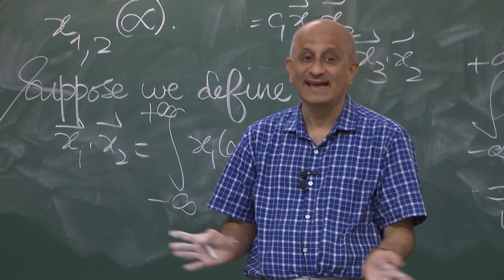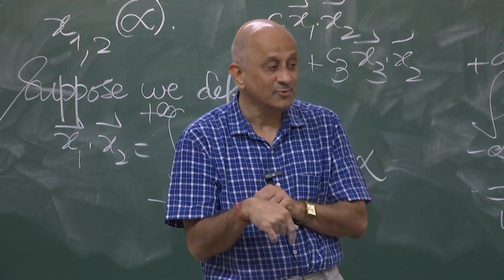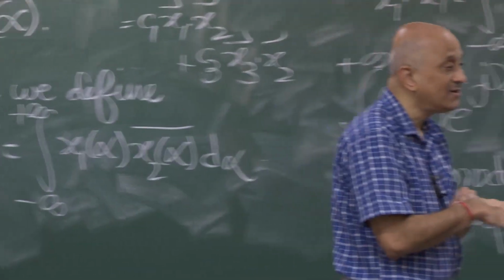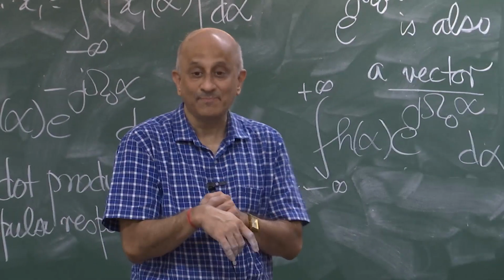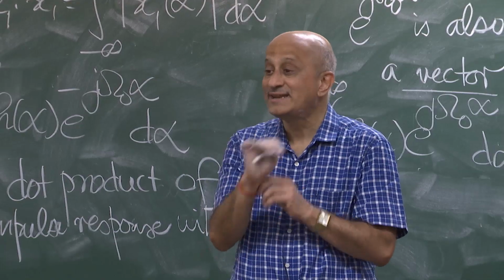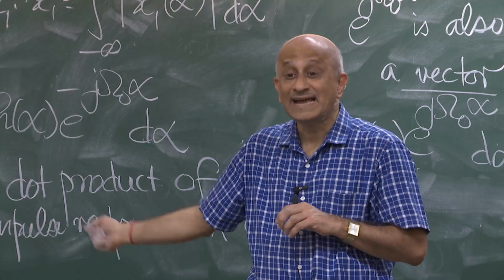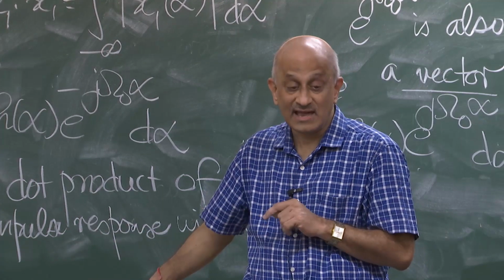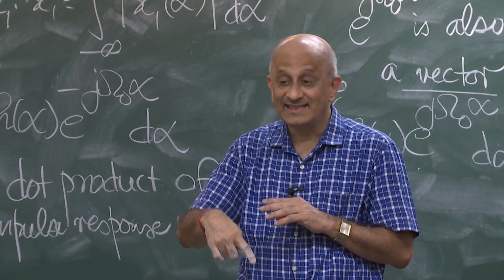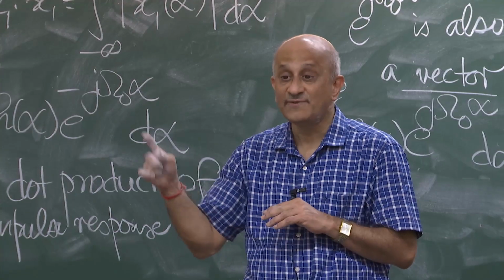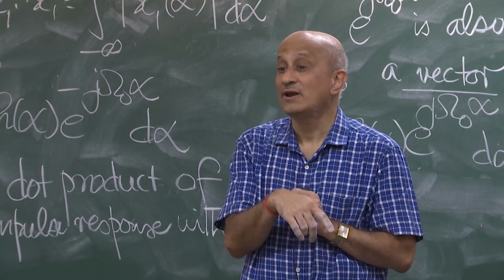So, it all fits very nicely, and that is the reason why we like to think of the signals that we apply in terms of these rotating complex numbers of different angular frequencies. And we know what happens to each of the angular frequencies. So, we can now combine the effect of each angular frequency and get the overall output.